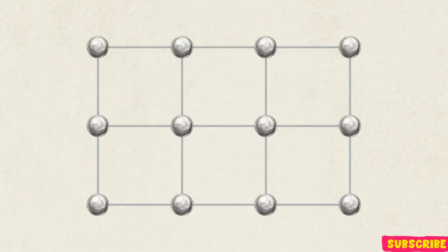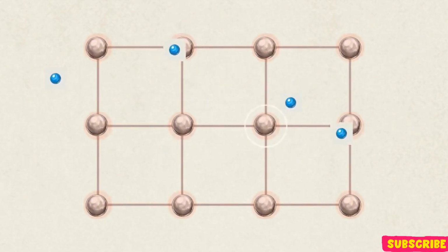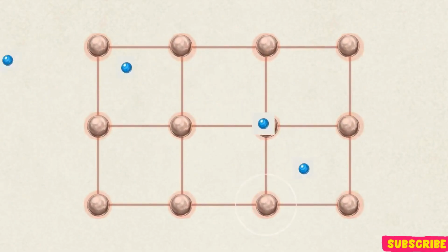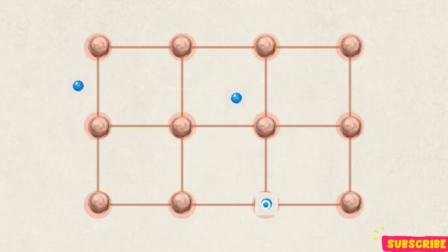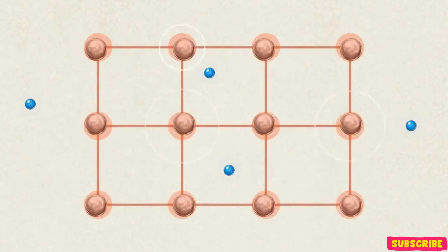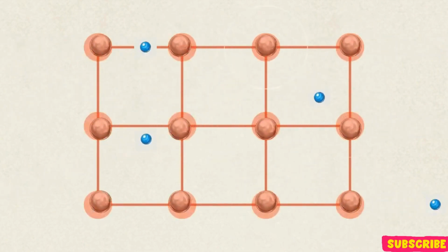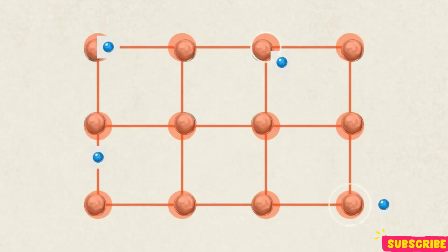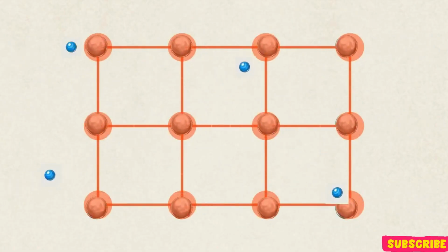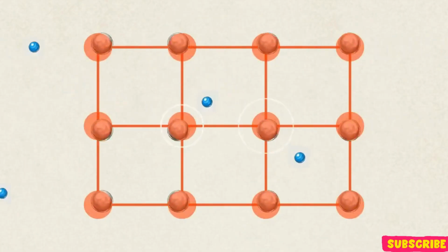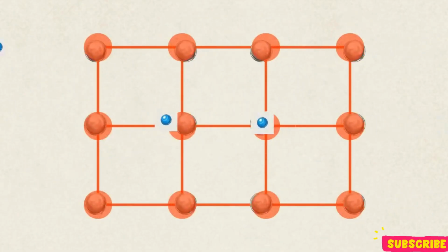This 3D model of an atomic lattice visualizes the mechanism of resistance. As the free electrons accelerate through the structure, they repeatedly collide with the much larger, relatively stationary lattice ions, continuously losing momentum and altering their trajectories. These are inelastic collisions. The kinetic energy lost by the accelerating electrons is absorbed by the lattice structure, manifesting as vibrational energy, or phonons, causing the ions to oscillate rapidly.